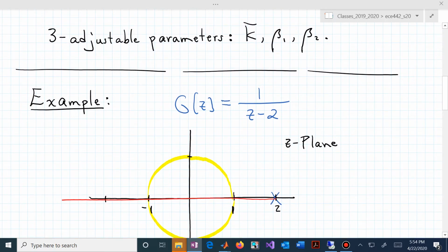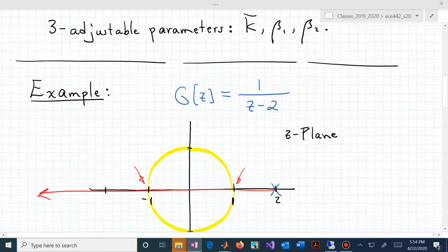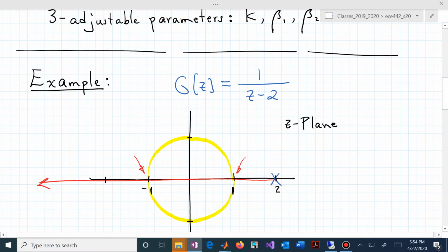We know this is the root locus for a pure gain controller. As long as we now crank up the gain to get us beyond z equal to 1 and not so high that we go beyond z equal to minus 1, as long as that one branch stays inside the unit circle, we can now stabilize that system. We may not be happy with the resulting steady state accuracy. We may be comfortable with the exponential behavior of the response, but now what do we do?